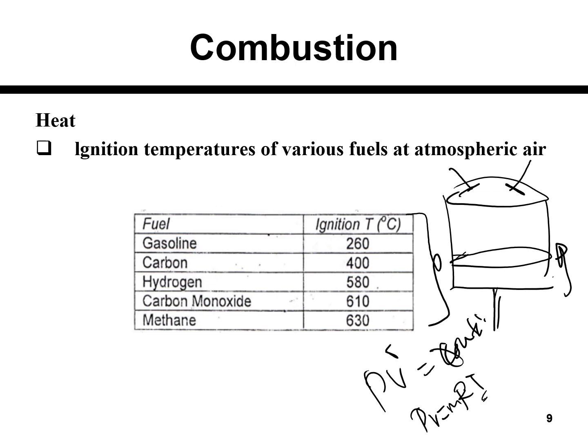The distribution of the temperature across the combustion chamber is not homogeneous. So some of the area will reach a higher temperature. For example, if this area achieves a higher temperature, the combustion will begin in this location.